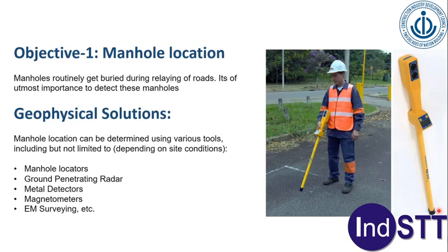GPR again comes in very handy for manhole location, as do metal detectors, magnetometers, EM surveying, etc. So there are different tools available for finding out the location of your manholes, which are otherwise not visible, buried under the layer of road, etc.